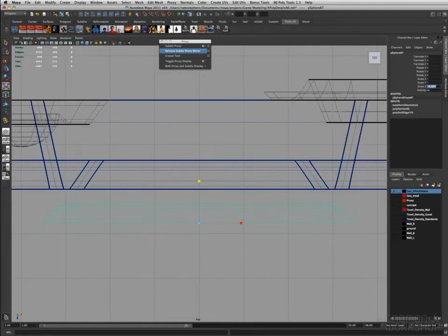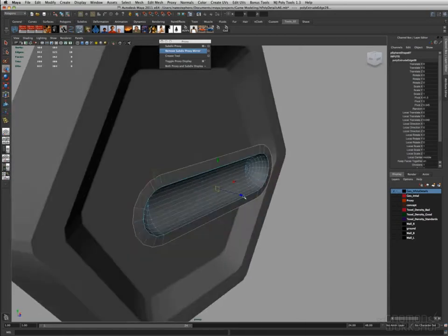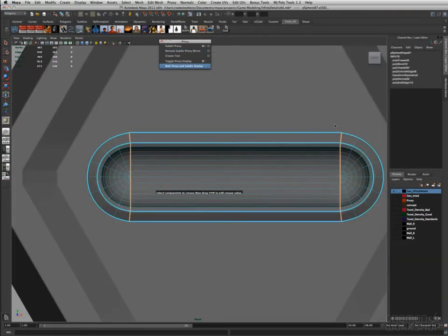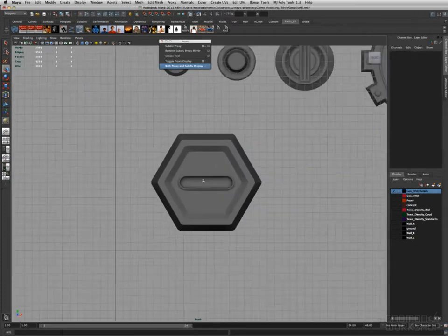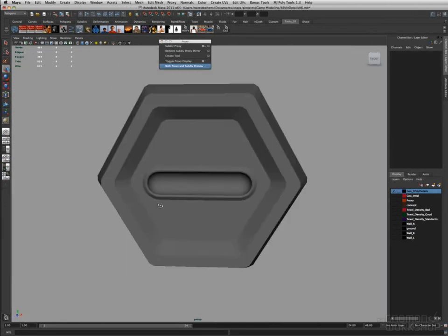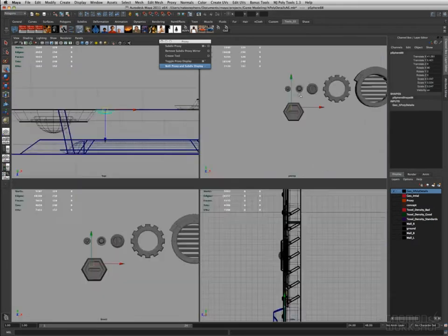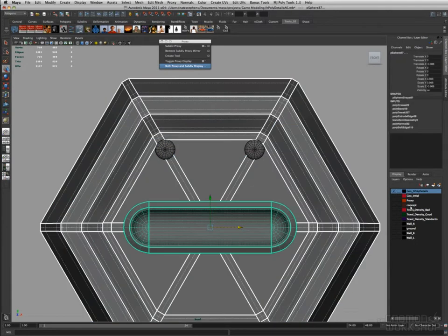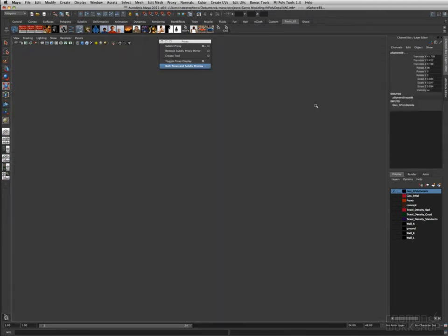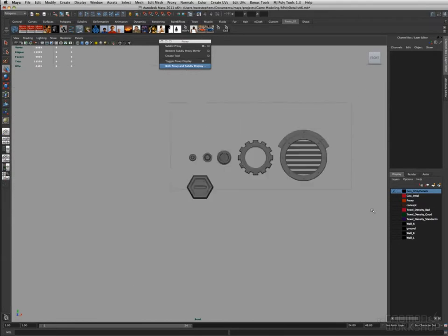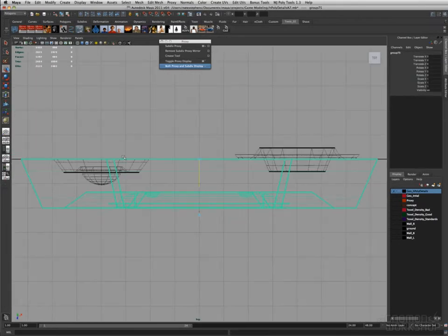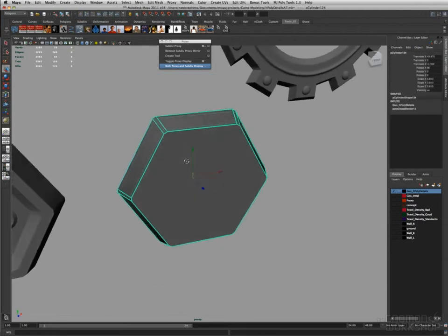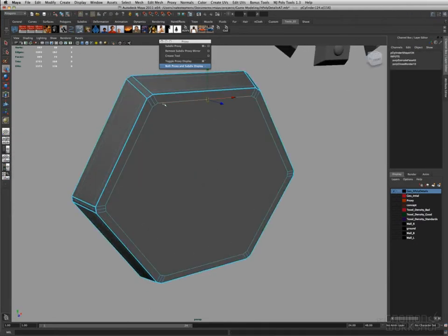And so what I'm doing right now is something that's referred to as a floater. Since I'm going to bake this down just to a flat plane, I can do some details that don't really even have to be part of the mesh. So this little guy will just be floating on top. It's not really stitched in. It'll give the illusion that it's kind of pushed back or recessed a little bit, but it's actually not. It's sitting on top of the geometry and floating there. But when we bake the normal map, it'll look like it's embedded in the face. And that's what's cool about this kind of modeling. It doesn't have to be right. This one just has to look right.